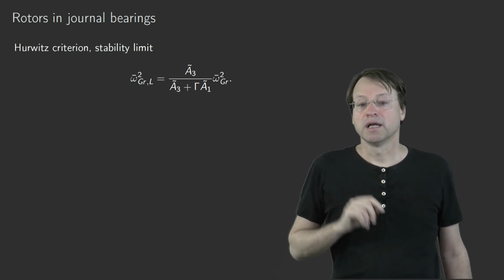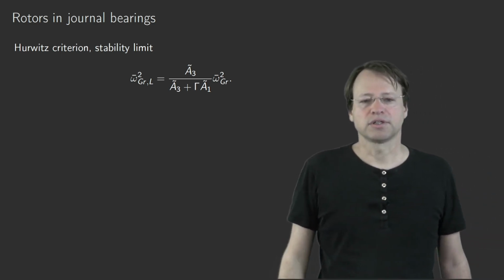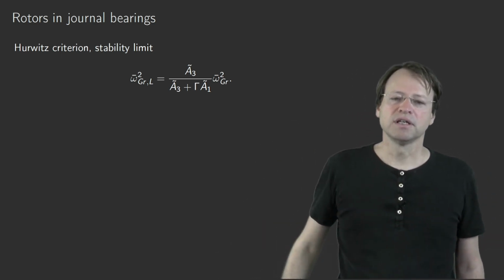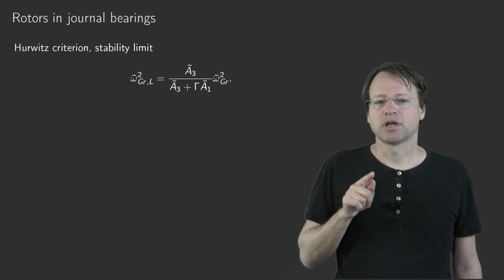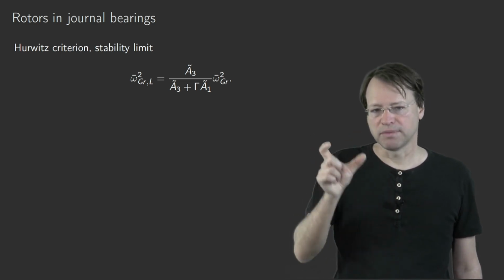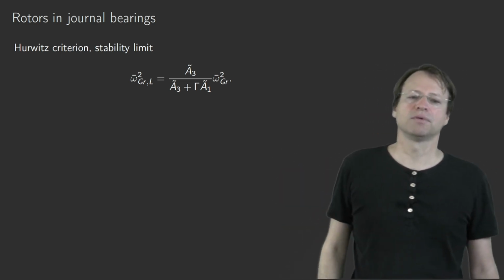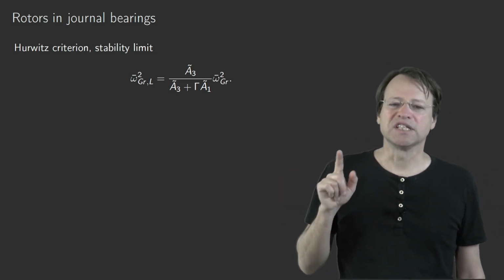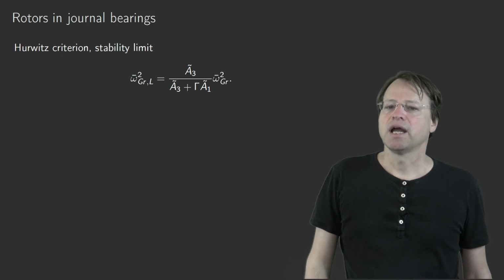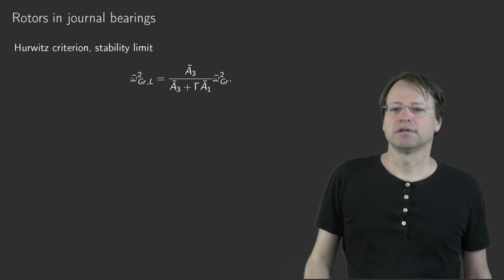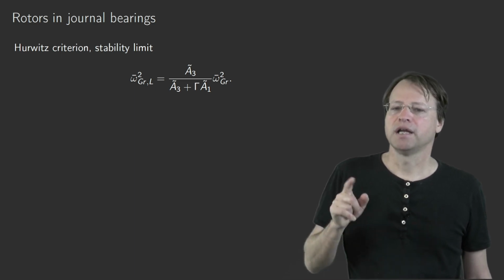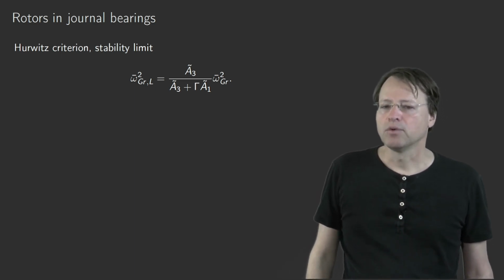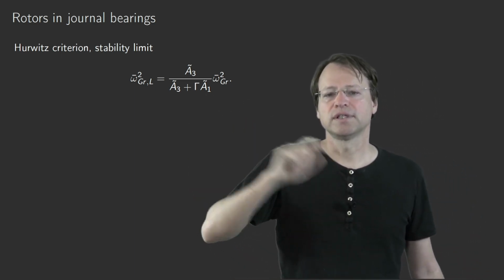Of course, the criterion is the same. We have flutter instability, but that flutter instability does not relate now to H3. Our Hurwitz matrix, as the characteristic polynomial is of order 6, is now a 6 by 6 matrix, and the corresponding Hurwitz criterion is now H5, the minor Hn minus 1. And what you get is the following result.